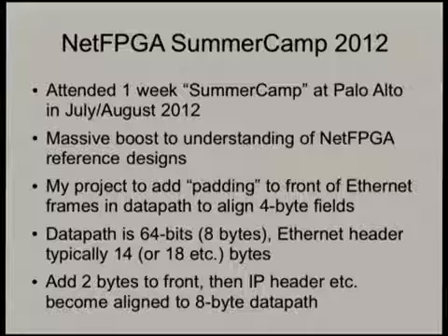Okay. So the question is why are we even bothering putting USB on a gigabit switch implementation? Thanks for asking that question, Martin. I did miss some key information. These ARM system on chips are designed for mobile devices, and mobile devices rarely require a wide network interface, so they don't have them. They do have USB 2. So if you want to get data in and out of these low-cost, low-power ARM devices, you have a number of options, but USB 2 is probably the fastest option.